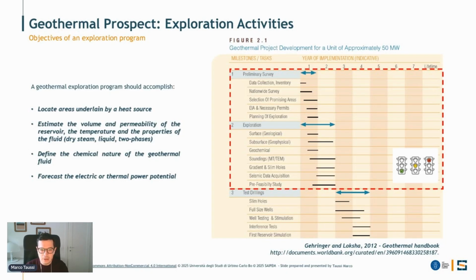Therefore, the exploratory phase is very delicate, requiring detailed analysis of various aspects, aimed at evaluating the heat source and providing an estimate of the volumes, the reservoir's permeability, the characteristics, the temperature, and the properties of the geothermal fluid. Finally, it is important to evaluate the extraction potential in terms of electricity production or thermal production from the reservoir, whether at high or medium-high temperatures.